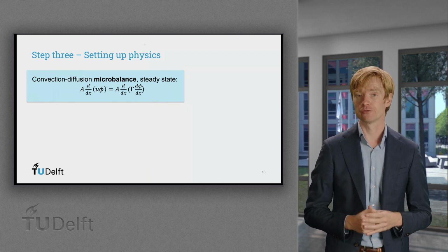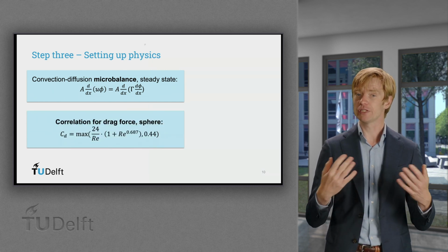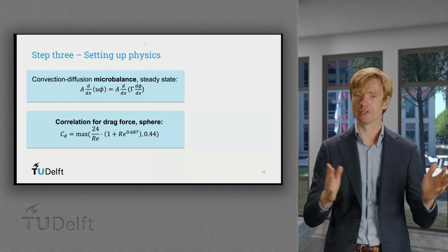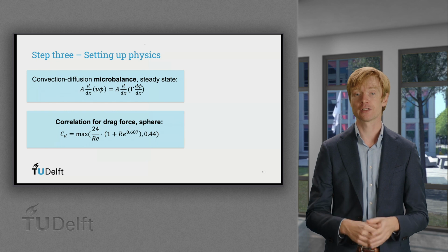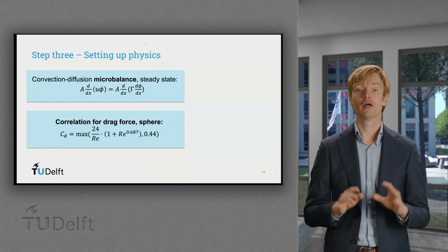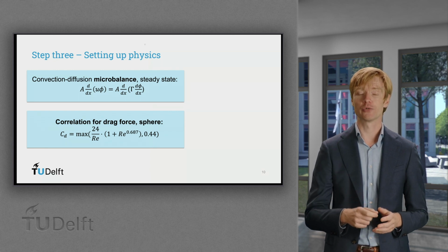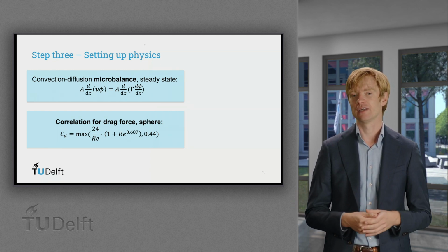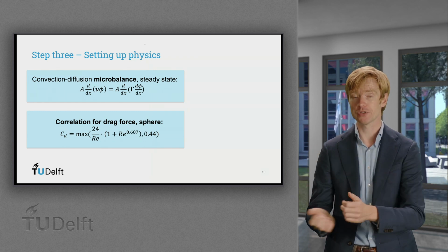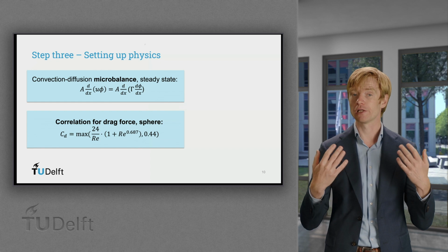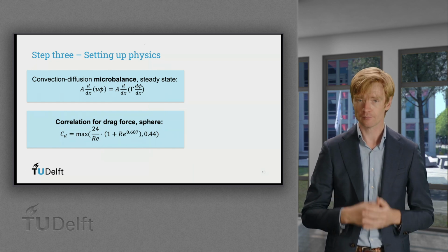Sometimes these models are based on physical laws, but often they rely on measured correlations. And that means that these models are typically applicable in a limited range of situations. Hence, several models may exist, each for a different scenario. And one of the major challenges for a CFD engineer is selecting the right models for any given situation. And this is typically where the discussion between CFD engineers and bioprocess engineers is important, because the latter probably has much more insight in which phenomena actually matter.